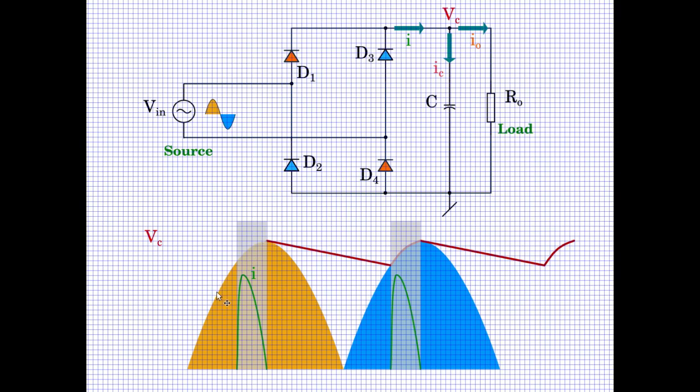As the capacitor is building up the charge, there is current flow to the rectifier, and therefore the rectifier current will be for this whole half cycle. So you will see the conduction period will start increasing and it will be for the complete half cycle. Likewise, the current wave shape also will get modified something like this.